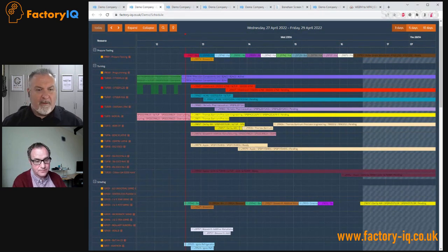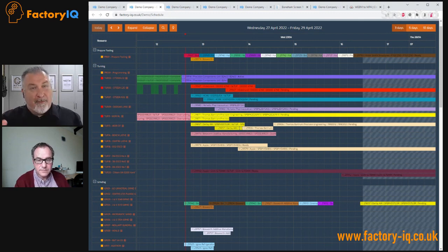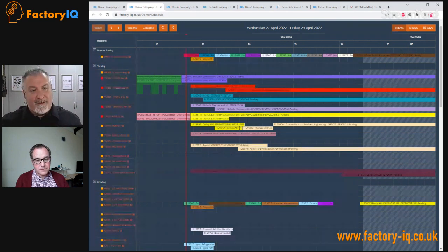And this for me is one of the big issues I had within the shop floor, and the reason we did this: seeing uncontrolled standard work instructions. This allows us to control it from a quality management system point of view, that it's online in one area, one central resource, and we can actually control it. So from a quality point of view, if we change any of the documentation, we haven't got out of date information on the shop floor in paper format. So we can always come back to the latest revision of what we're doing.